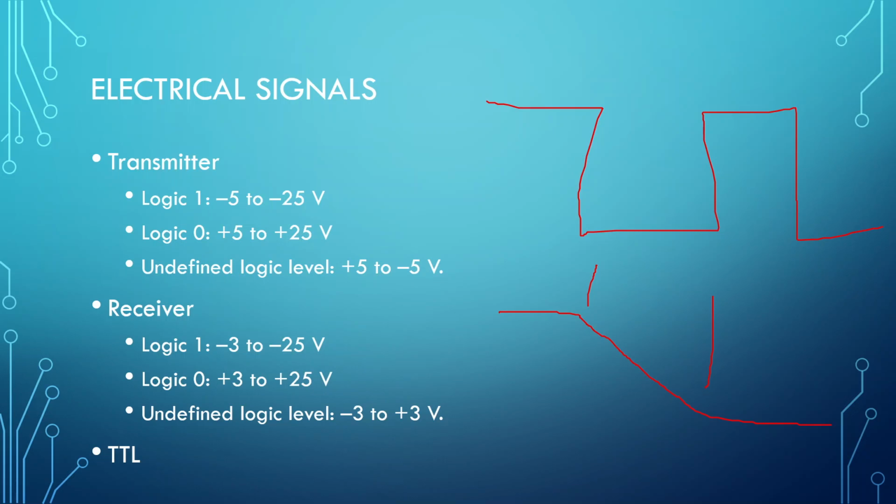But anyway, transistor level is instead of -25 to 25 volts, 0 to 5 volts. So instead of such high voltages and big distances, we only have these little voltages. The reason for that is what computers actually deal with. They're normally smaller voltages. Especially older microcontrollers or Arduinos, for those who have heard of those, the older ones are 5 volts.